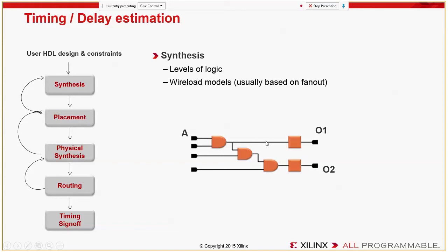There are also some wire load models that will try to make a guess of what the placement might be based on the size of the logical hierarchy in which an instance or a net is found, and so on. These estimates are fairly inaccurate, and so at this stage, basically, fidelity or the ability to distinguish a good move from a bad move is more important than an accurate estimate of delay.